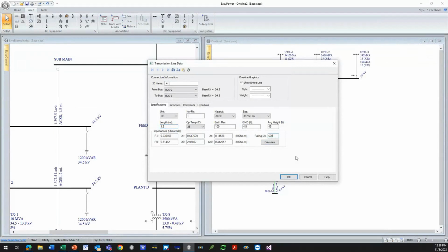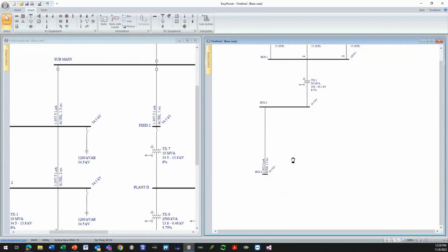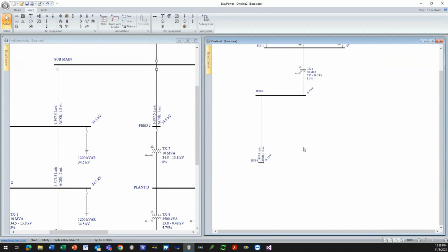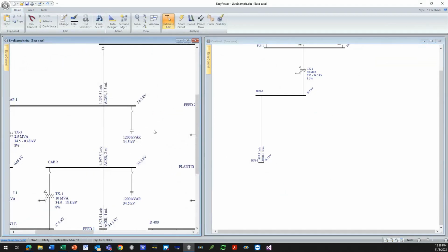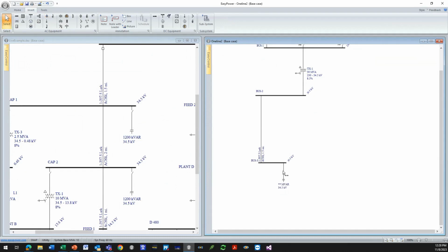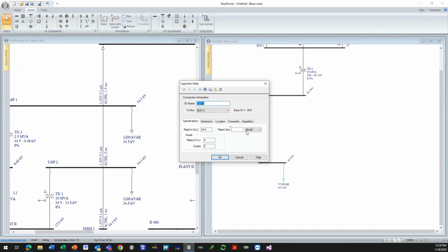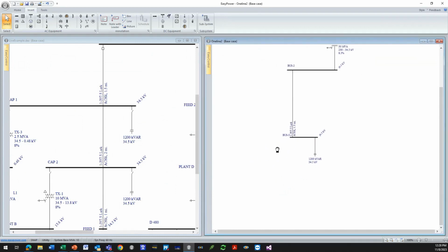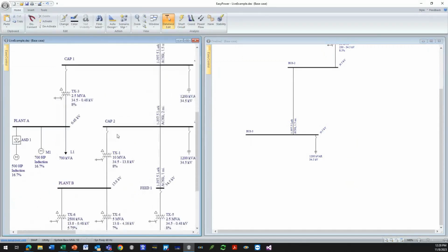It automatically generates your ampacity as well. So you can tell this is set up for more than harmonics. I mean, this is going to help you perform power flow simulation, short circuit. Interestingly, on this bus, there is also a capacitor bank, 1200 kVAR. kVAR, 1200, enter. Okay, I'm going to put a switch on here in case I want to turn it on or off. Now, I'm not going to continue like with every single one of these subsystems, but let's take a look at,